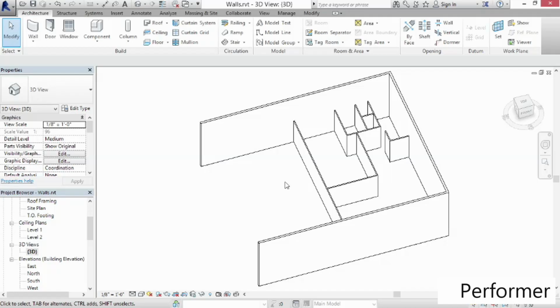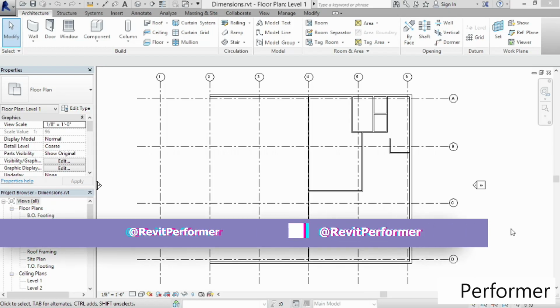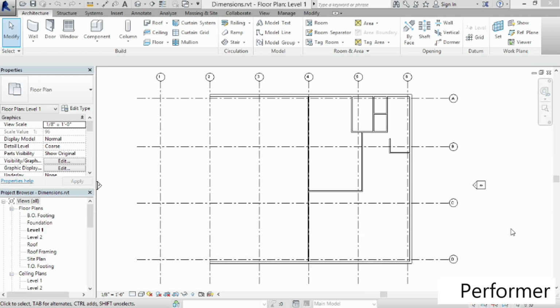That's the basic process that's involved in laying out some walls. You can either lay out the walls very precisely relative to a column grid or some other geometry, or you can lay them out in a very rough fashion and then come back and modify them later. The choice is yours, and it really depends on what you're trying to achieve. In early schematic design phase, it's okay to rough in the locations of walls and other geometry where you think they might go, but at some point you're going to want to refine those layouts and make them a little bit more precise. Now in Revit, we do this primarily with dimensions. We have other ways, but dimensions provide a really quick and easy way to move geometry around. And so in this movie, I'd like to show you 2 kinds of dimensions, temporary and permanent dimensions.